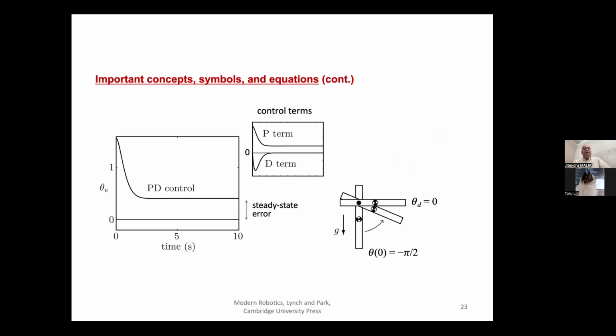Okay. And so what this says is, again, you can do simple-minded stuff. Suppose you did not have the integral term and you just had a proportional control, so there are variations. We call this a PID controller. You can have a PD controller. PD controller means that you don't have the I term. You can have a P controller, which means you don't have either the I or D term, right? You can have a PI controller, which is you just have a proportional and integral term. So all these variations are possible.